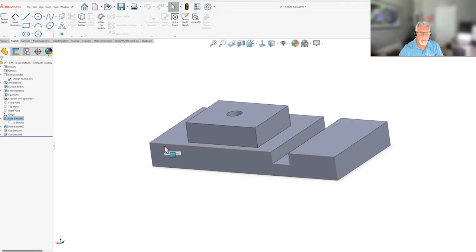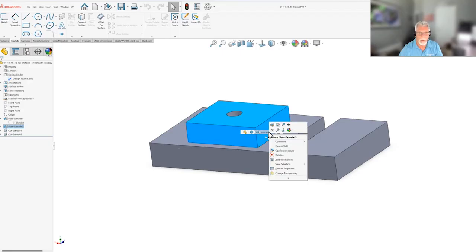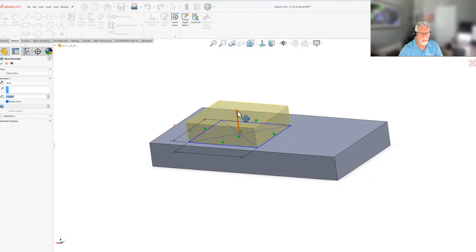But that's the reason for the breadcrumbs, you can get it down here versus I can always go over to here, but I may not know where it is in the tree. Usually when you select it, it highlights, right? But by putting it here, I can go to the sketch, I can go to the boss, and I can redefine those right here by right mouse clicking. Does that answer your question?